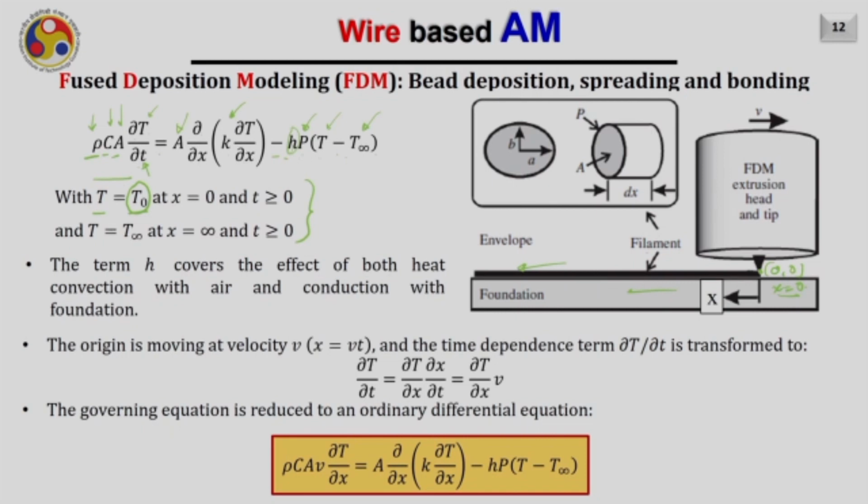Also, at x equals infinity, meaning very far away from the nozzle, the temperature of the bead is equal to T infinity, and this occurs after a very long period of time. Okay, so we are considering this condition for the steady state only.